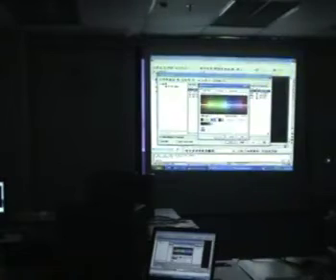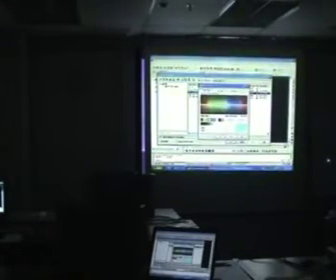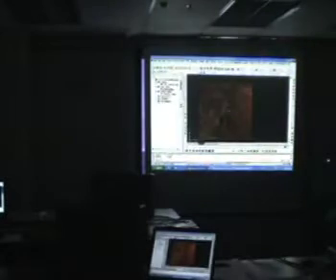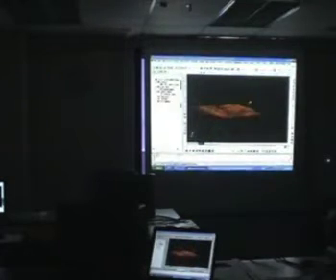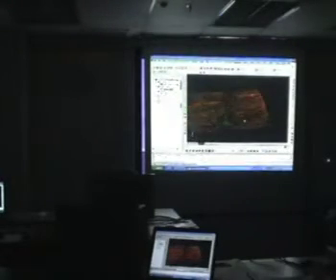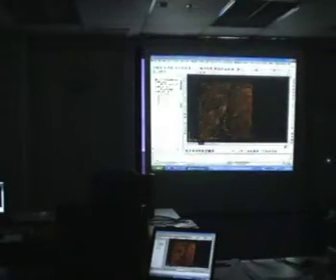So let's say I want to change the color. The major lines, I put them as green. Switch minor maybe to red. More visible difference. So you can actually see the contours minor and major. Again, they are also in 3D. So if I orbit, you can see them in 3D. It's not so apparent as the triangles, but you can still see them in 3D. So I'm just going to reset the view back to the top plan and zoom into the contours.